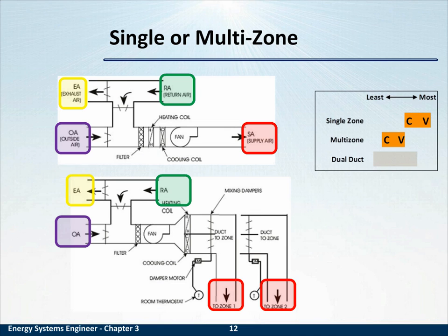Each zone with its own duct mixes heated and or cooled air using the mixing dampers to provide the right air condition for that space. Strictly speaking, and easily seen from this picture, in a multi-zone the number of zones refers to the number of supply air ducts.